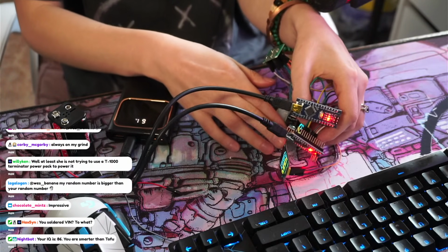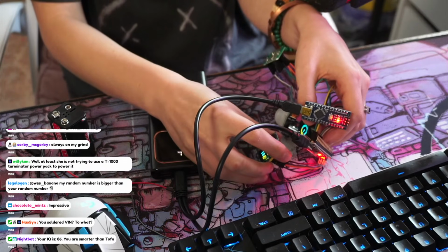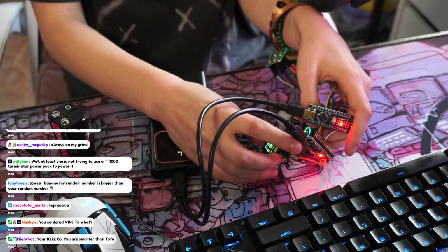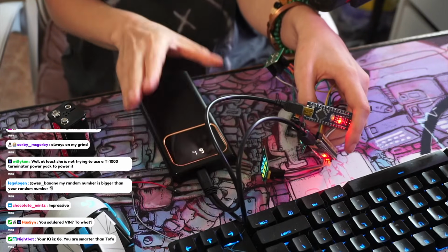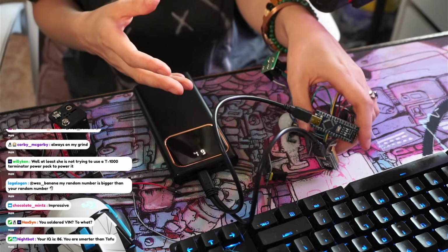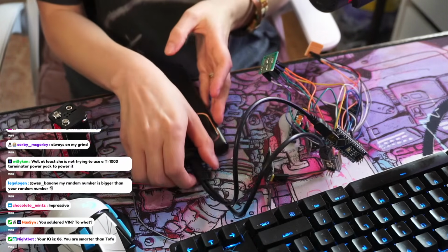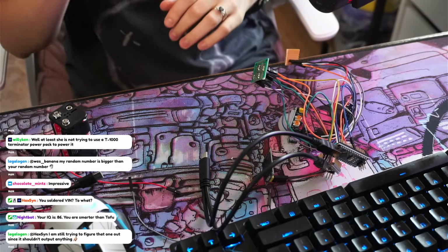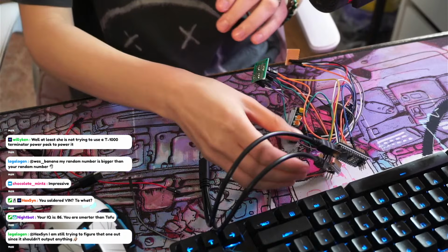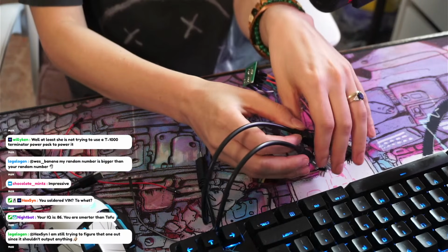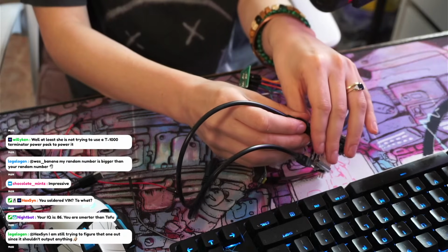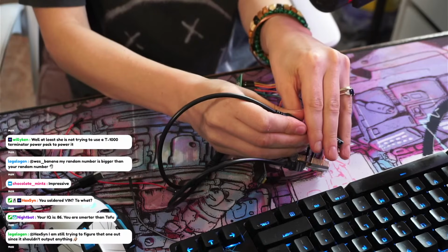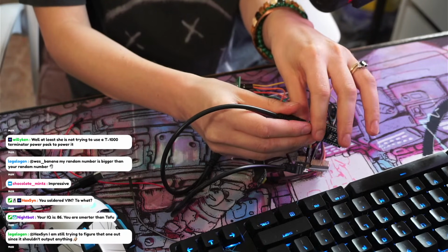So this was our original model. We would use a power bank to power everything. The problem is that it's too clunky, it's too big. I hate the power bank, so that we want to remove. No, we didn't solder the VIN. Sorry, we didn't solder it. We had it plugged in, but I changed the VIN to 5 volts. All good, it still works. So now our VIN is available. Our ground isn't. We were basically using VIN as a 5 volt source.